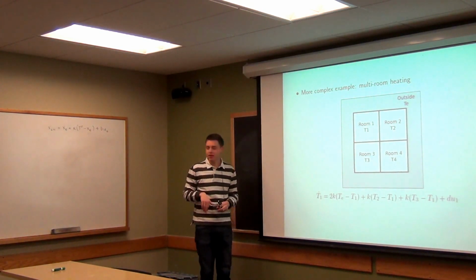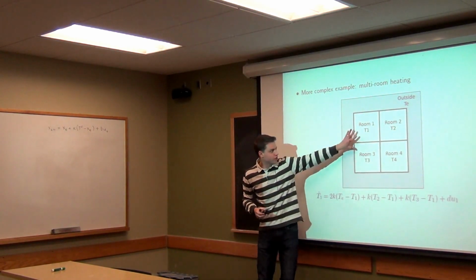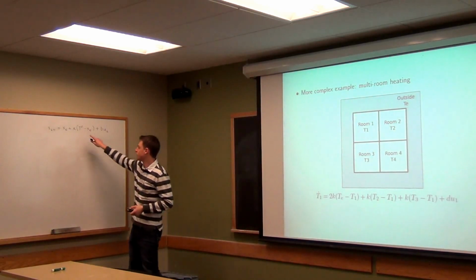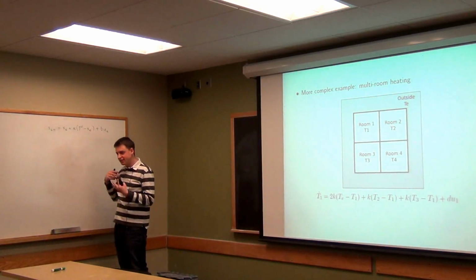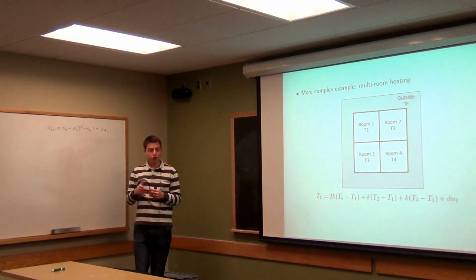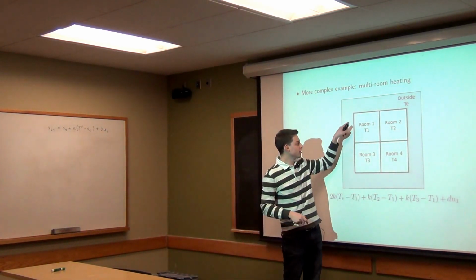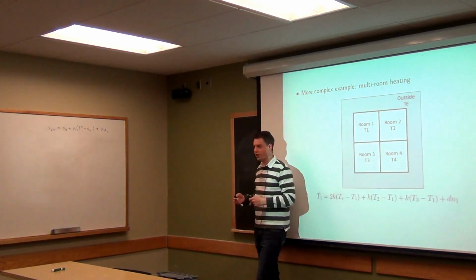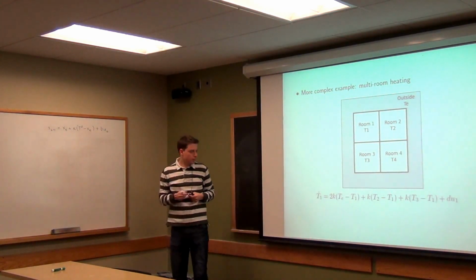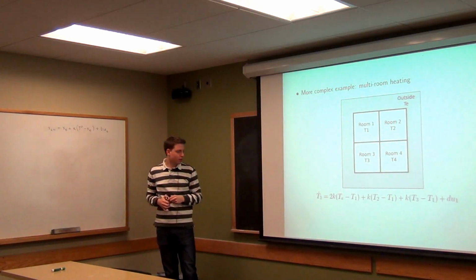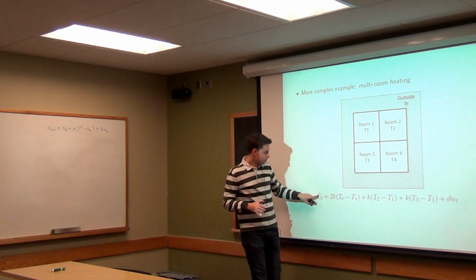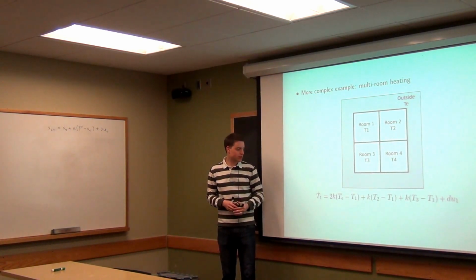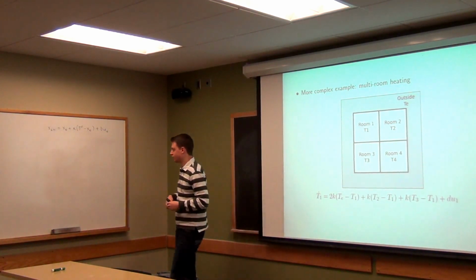But anyway, regardless of that, the temperature in room 1 will evolve according to the same equation. It's just that now this external temperature isn't just the external temperature, right? It's now the external temperature on 2 sides plus room 2 and room 3 on other sides as well. So the way we can write that, and I'm writing it as a continuous time case here, even though we'll really solve it in discrete time, maybe I'll just write it here actually in discrete time.